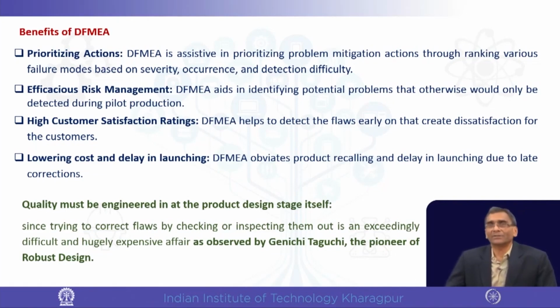Suppose there are 10 parameters to be tackled. We have to change one after another and see which parameter or variable leaves what kind of impact. Suppose there are only 3 factors, and each factor can have a maximum value and a minimum value, then you will find only 8 experiments are to be carried out.